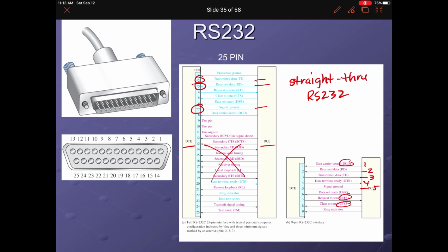And if I go back to the slide I did on the telephone modem, remember these DCEs over a single line, these DCEs are responsible for communicating full duplex, where you had a carrier that was taking data this direction at the same time a carrier that was taking data this direction. And because of that, you essentially had what was called a transmit-receive crossover. You had it such that a signal leaving here on transmit data would end up being interpreted by the receive data on the other end. So you had a transmit-receive crossover. TX here ending up on receive here, and TX here ending up on receive here. So that data was this direction, and that direction at the same time, giving you a full duplex.